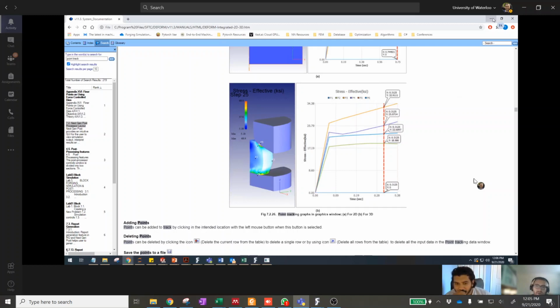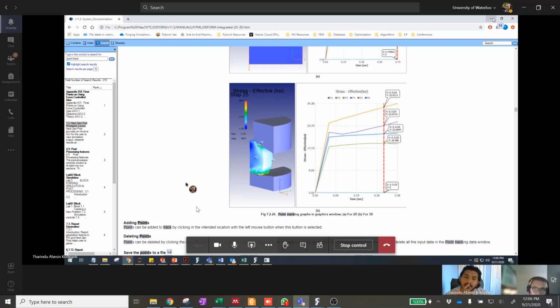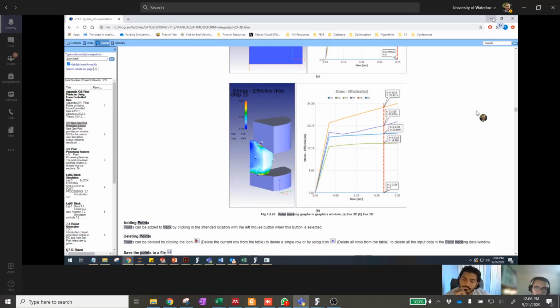And the other reason why I wanted to graph these quantities is because we could go through the plot and maybe the axial stresses start very low when you get to 17 megapascals and 21 megapascals of shear. But where we're looking at them, you're really, really far in the deformation. And because the whole element's rotating a lot, it might be causing the axial stress. Like maybe if you go back,